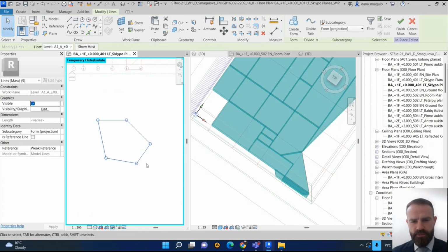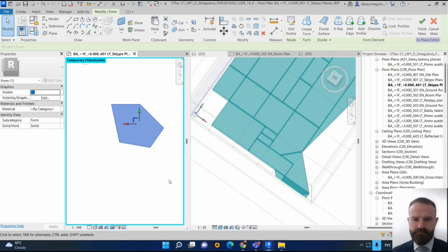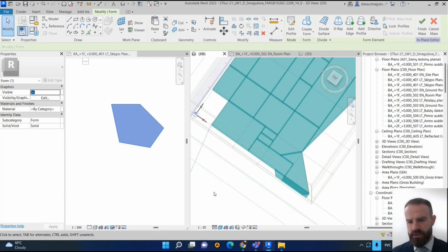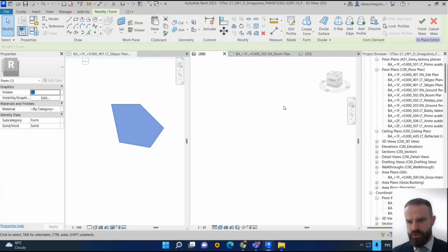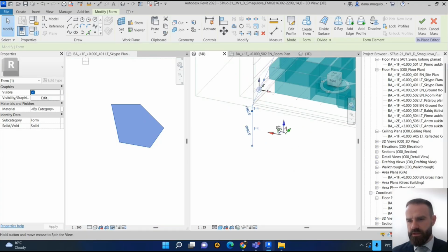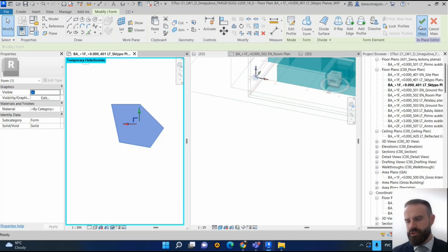Select, click on this shape. Yes. Now in the menu you can see create form. Click on this object, create form on the top right side. Sorry. Yeah, this one. And you should jump in 3D model. In 3D model, yeah. So it's cropped. Okay, so you can click finish mass and remove scope box. Click finish mass, yeah.